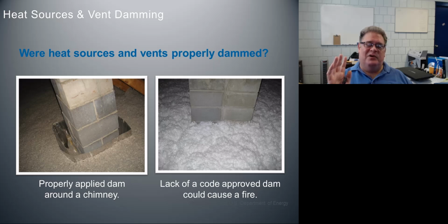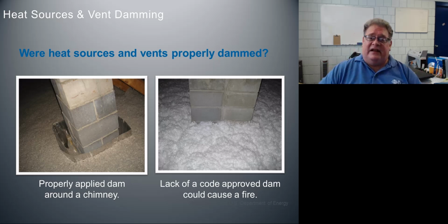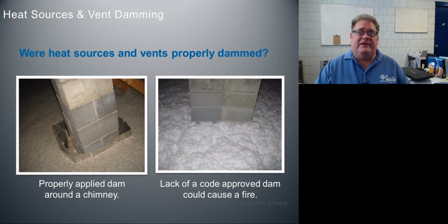All right. My question for whoever put these slides together, or is fussing about the code-approved dam, and these photos are courtesy of the Department of Energy, all right, is what is the material of this insulation? If this is fiberglass, then we need to look at the manufacturer of the fiberglass and see what they say their fire rating on that is. I think you're going to find that blown-in fiberglass insulation does not burn. Okay, in other words, it's not a flammable, it's not a combustible, it doesn't need to have that clearance. So then my question becomes, do we need a dam there or not?